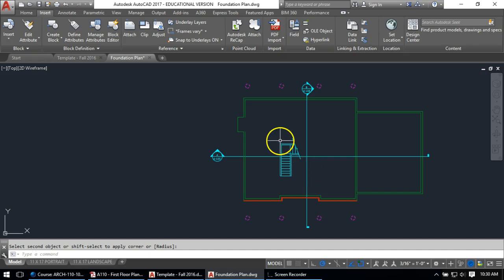The next thing I'm going to do is start laying out the interior walls. Now, one of the things you'll notice in this floor plan is that a lot of the interior walls, as well as the windows and the doors, are all dimensioned from their center point. And you'll note, if they were measured to their edges, it certainly would be a lot easier to draw in AutoCAD if you're just copying it as we're doing here. But there is a specific reason why they're marked to the center point.